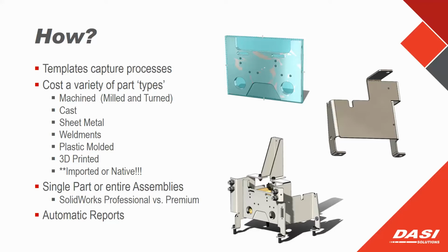Now, weldment components, or multi-body components in general, which could be mixes of welded or structural members, sheet metal components, and machined components, frankly, can also be done. And that is a multi-body part. So not an assembly, not individual part files, but a single part file with multiple disjointed bodies. Works a lot like an assembly, but in this case, single part file.